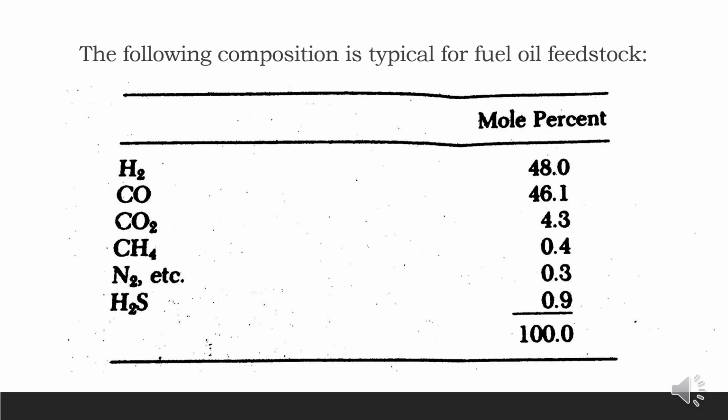In the commercial application of the Texaco process, preheated oil is mixed under pressure with oxygen and preheated steam and fed to the partial oxidation burner. About 26 cubic meters of 95 to 99% oxygen is used per 100 cubic meters of hydrogen with CO produced.